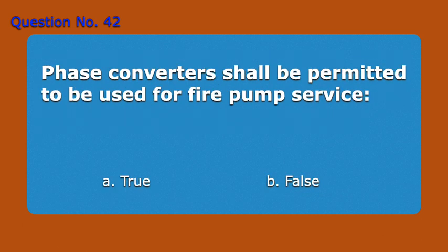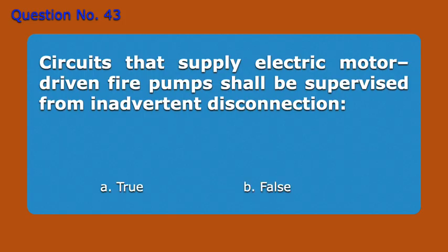Question number 42. Phase converters shall be permitted to be used for fire pump service. A. True. B. False. Answer B. False. Question number 43. Circuits that supply electric motor-driven fire pumps shall be supervised from inadvertent disconnection. A. True. B. False. Answer A. True.